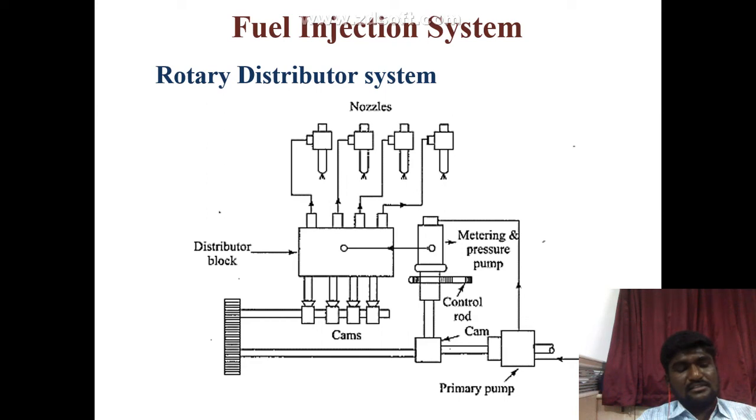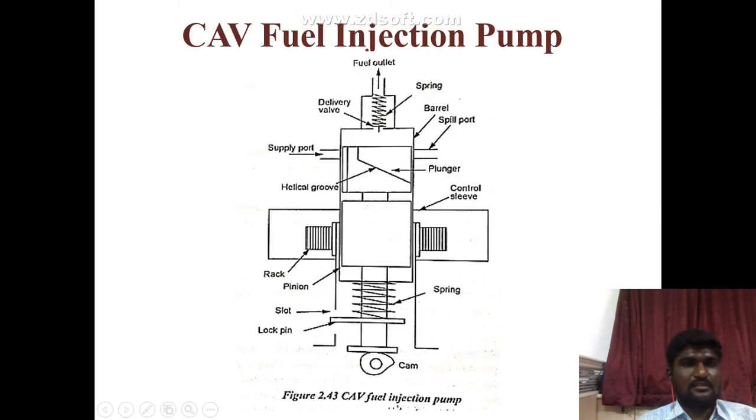The fuel is distributed to the cylinders in the correct order, operated by poppet valves, which open to admit fuel to the nozzles. Distributor pumps usually have controlled sleeves for the metering and injected quantity. It is easily controlled by electronic solenoid valves, solenoid actuators, which regularly regulate, control and monitor, right?